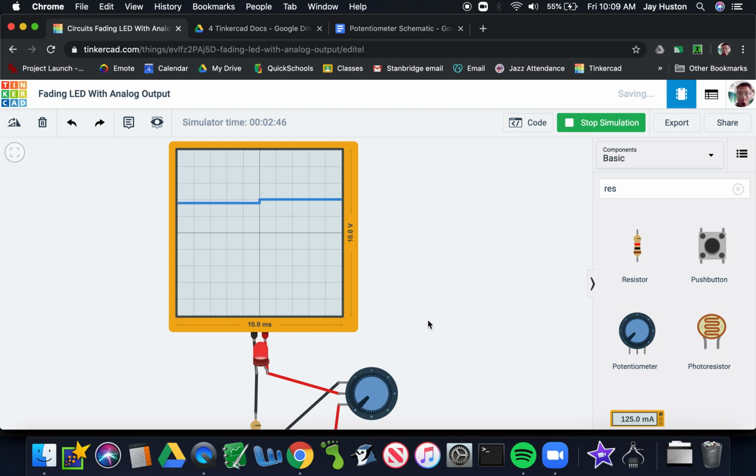So the difference between the potentiometer and the Arduino dimming this is that the potentiometer is actually changing the voltage. We are getting voltage that's in the middle. Like right here, it's 4 volts, right? And if I drop it to here, it's still hanging out around 4 volts. What about down here? What does that give me? Oh, 2 volts. Woohoo!